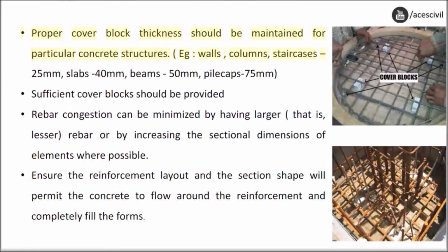Proper cover block thickness should be maintained for particular concrete structures, e.g., walls, columns, staircases 25 mm, slabs 40 mm, beams 50 mm, pile caps 75 mm.